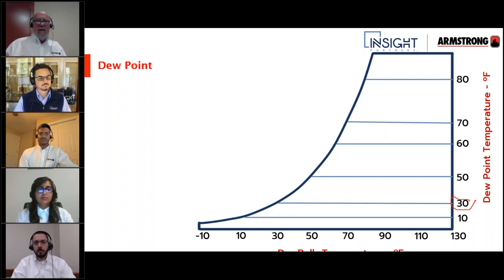We do the same thing when you're building a data center. Let's say you're going to build a data center in a building, and you want that data center to control to 50% RH all the time. You have to put a vapor barrier behind the wallboard, and a vapor barrier that covers the ceiling and the walls. Otherwise, the higher humidity in that space is always going to try to migrate out of that space to the surrounding areas. Humidity is always going to try to go into equilibrium, just like air pressure is trying to be in equilibrium everywhere in a building.